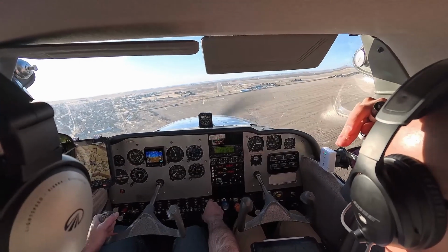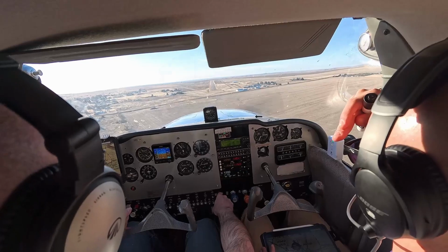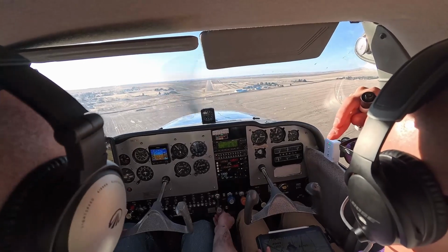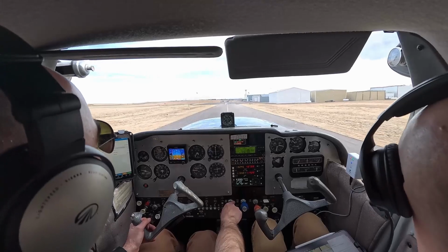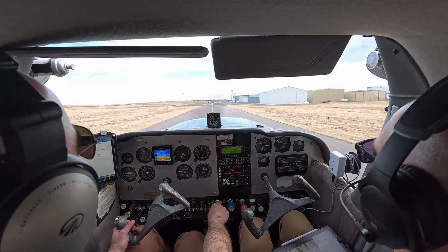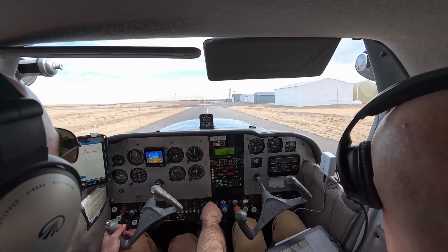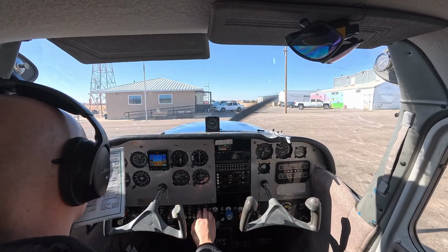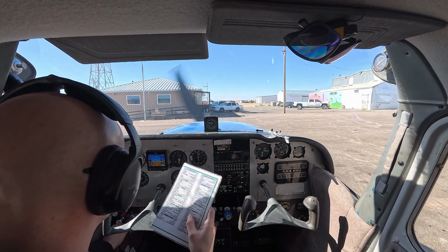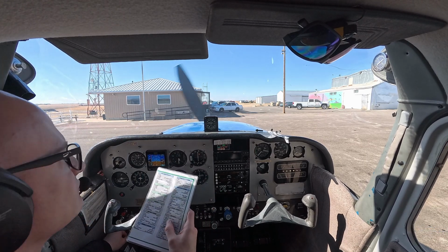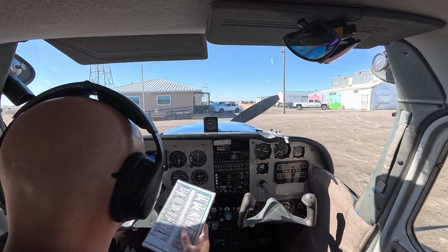The reason we go to the high performance setting for landing is in case of a go-around. All we have to do is increase throttle to the takeoff setting. Once you've landed, the propeller knob is all the way forward still, and you can once again taxi the airplane just as you would a fixed-pitch propellered aircraft. As you shut down the airplane and oil pressure is lost, the propeller will go to a fine pitch setting. And just like that, a normal flight is accomplished with a constant speed propeller.